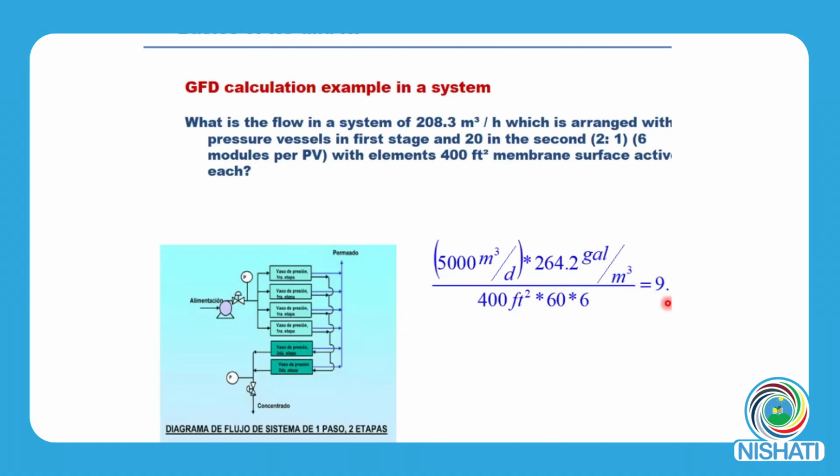Okay, so this parameter is important because it's telling you if your system is conservative or not conservative, depending on the water quality. Okay, if you need to treat very nice water, just containing some salts, almost no suspended solids, very few bacteria, very few colloids, you can increase the recovery very much.